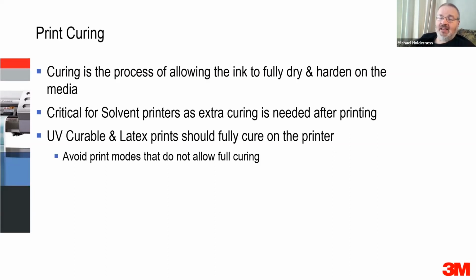What we're talking about is, if you get a UV print that comes off the printer that feels slightly sticky, get it out in the sun or put it back through again and try to get some more curing into that somehow, or turn up the lamp current or the lamp curing, because if your UV print comes out sticky, it's certainly not fully dry. I would try and get it out into the sun, but probably you'll be looking at reprinting it.